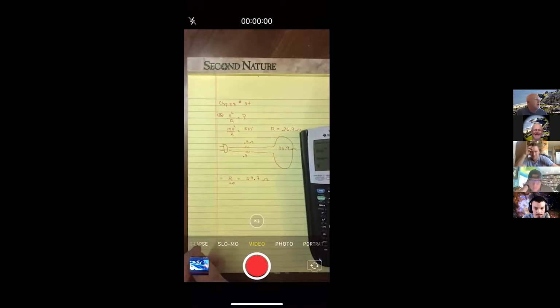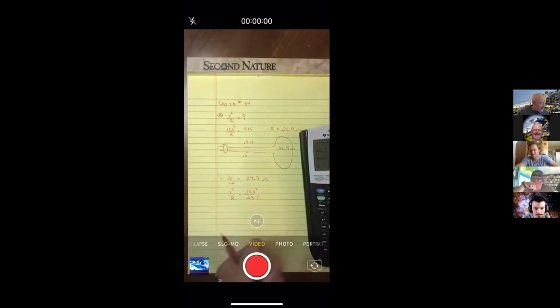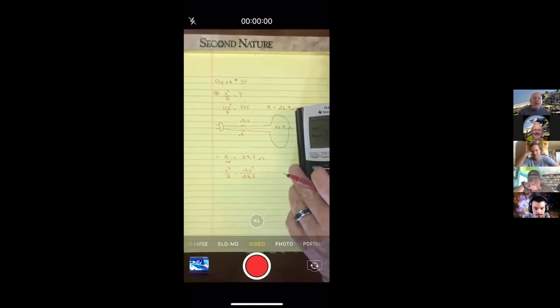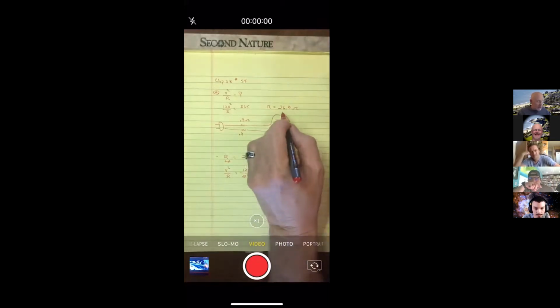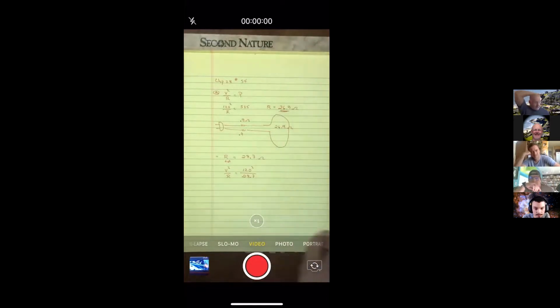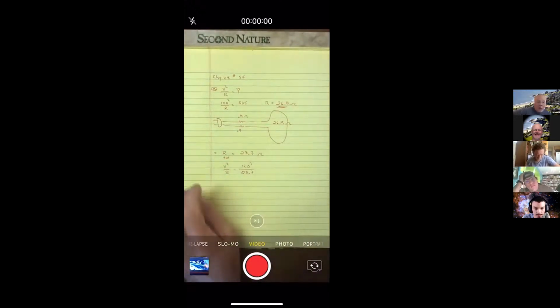If the resistance of each of the two conductors is 0.9, what is the actual power delivered? Then when I go V squared over R, which is 120 squared, I would have to divide it by a resistance that's a little bit more, the 28.7, than what was actually in the vacuum itself, because it's hooked up to the extension cord. Which is why some devices that are already just barely getting enough power to run will say do not hook up an extension cord. I know my air compressor is that way.